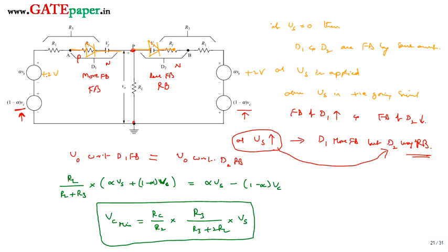If the control voltage is lesser than this value, then diode D2 becomes reverse biased for positive going signals, and for negative going signals diode 1 becomes reverse biased, where it cannot act as a bidirectional sampling gate.